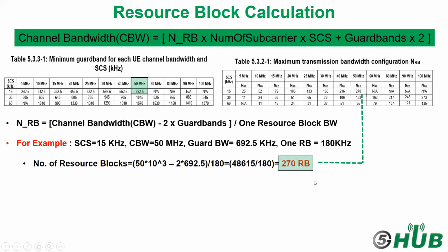This video was about the 5G new radio channel bandwidth, frequency range 1, frequency range 2, and what are the maximum and the minimum transmission bandwidths in each frequency range, and how we can calculate the number of resource blocks for each frequency band.